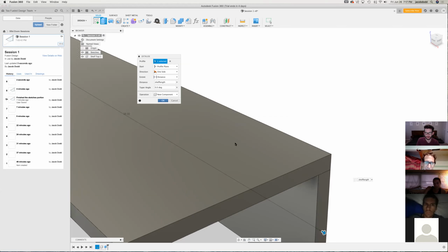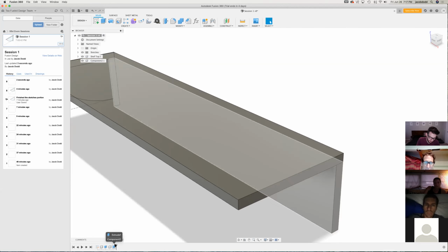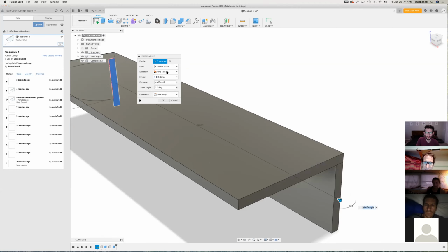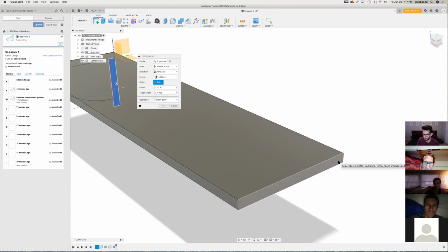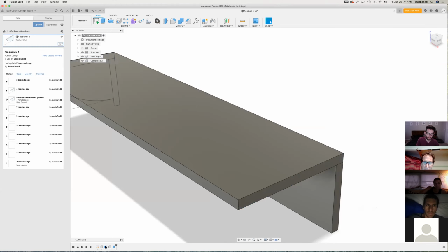So click OK there. Oh, sorry, real quick. I'm going to double click at the bottom on that last extrude we did and give an example here where it says extent. Instead of distance, we can actually do to object and select the face on the end here, and it will have it go to that face. Now, will that also keep that extrusion the same length if we change the one that we said? Yes. Because in the measurement it says 2 there, right?